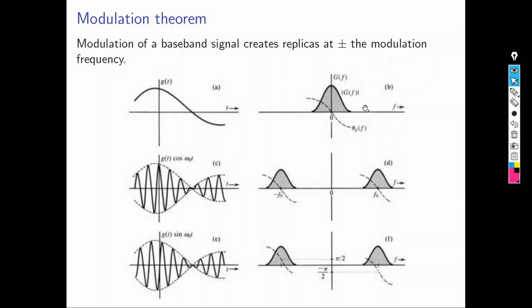So you multiply it by the carrier frequency, and I tell you draw the spectrum after modulation. You find out that it's a replica of the message itself, but instead of being at zero, it's now at the carrier frequency Fc.